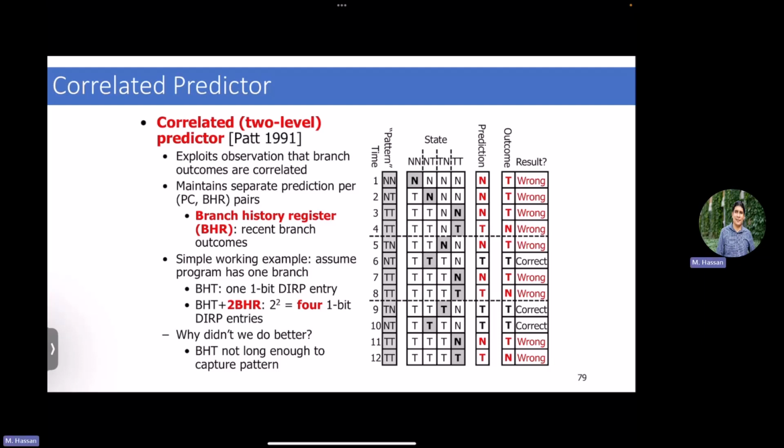Right now, what is the directly previous state of the two branches? One of them was taken, which is the J, and the I is still not executed at all, so it's still N. So I have to pick the prediction from the state of NT. So my current state in NT is this one, so I'm going to predict it's not taken. I predict it's N. I'm still in the J, right? Because I executed J only once.